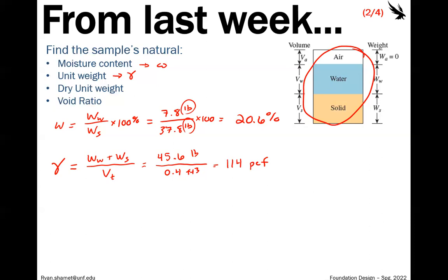On the other extreme, concrete, which is close. Yes, 150 pounds per cubic foot is concrete, and we can all picture what concrete is. Maybe you've picked up a piece of concrete. It's really dense, and rarely do we see soil that is denser than concrete. If you get into rock mechanics and you're working with granite and other massive rock forms, then maybe you'll see it above 150.